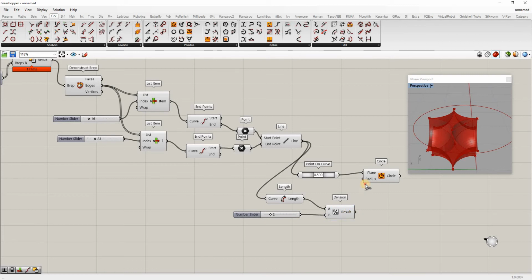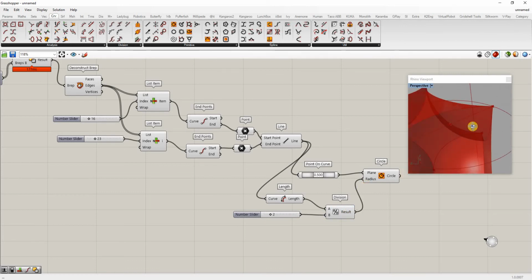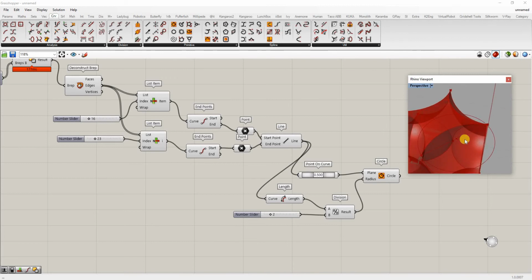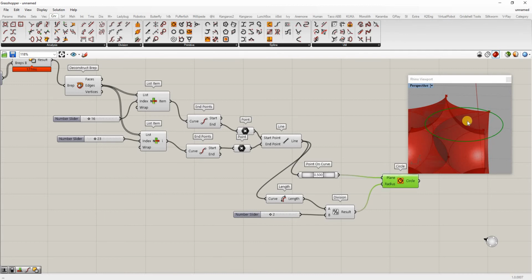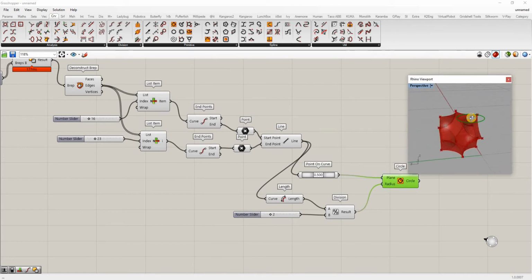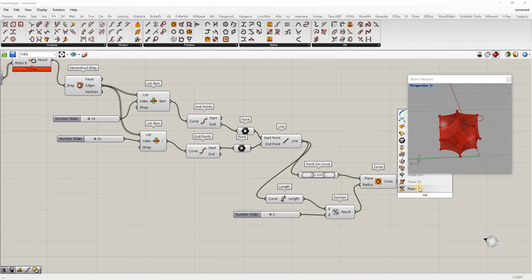So then I'll have the radius of a circle that matches that. Now, to make this sort of saddle shape, I need that in a vertical direction rather than a horizontal direction. So I'm going to rotate this circle. Let's rotate it 3D. This geometry, the center point is going to be our center point that we made that on.